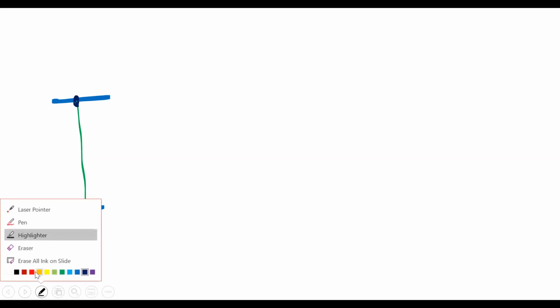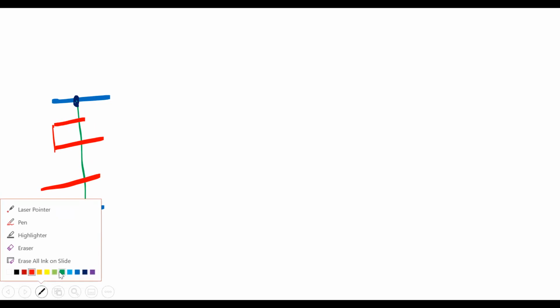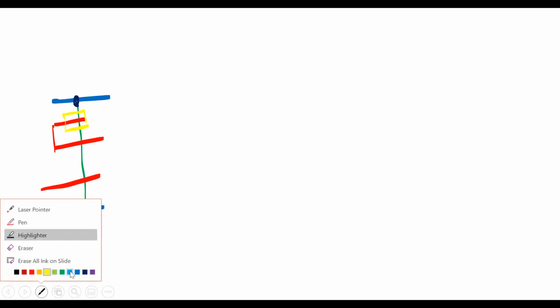Next are the contact cuts. Next, polysilicon, red color. This is one poly. Here is one more poly. Now the implant, yellow: a small yellow rectangle box should be provided, and inside that there is a buried contact that we can show like this, with dimensions like this. Okay.